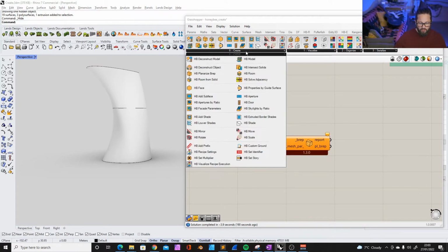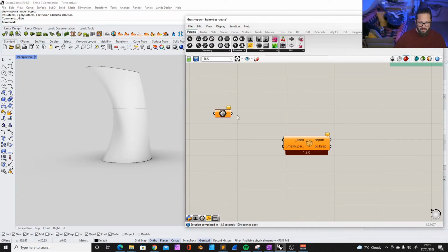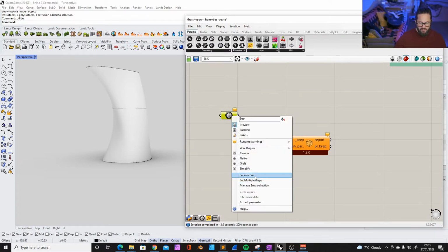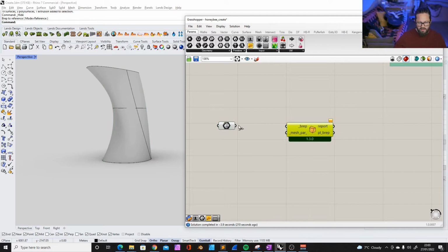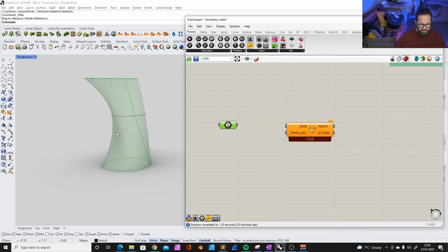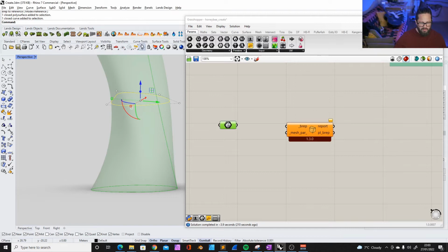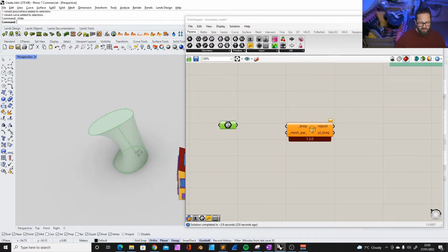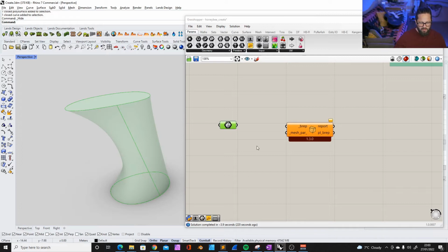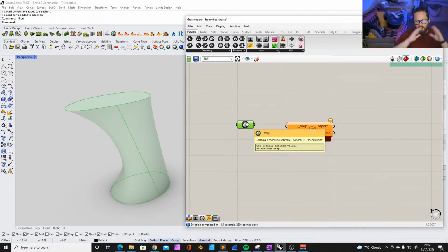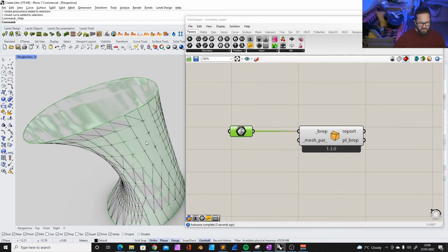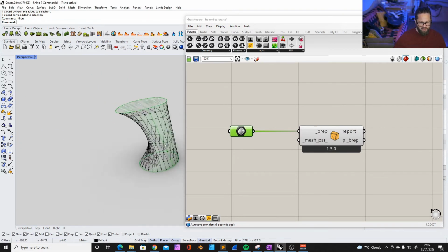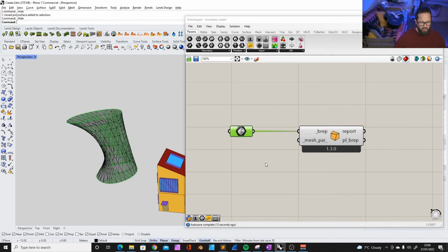And what we need to do first is to put this in a B-wrap container and set one B-wrap. Yeah. So now we have this here, and what we need to do, because Honeybee needs more simple geometry in order to run calculations. That would be difficult, and basically you need to planarize or facet your round shapes or curves. And just put this in here, and you can see that it created a mesh object. I can hide this. So this is my object now.